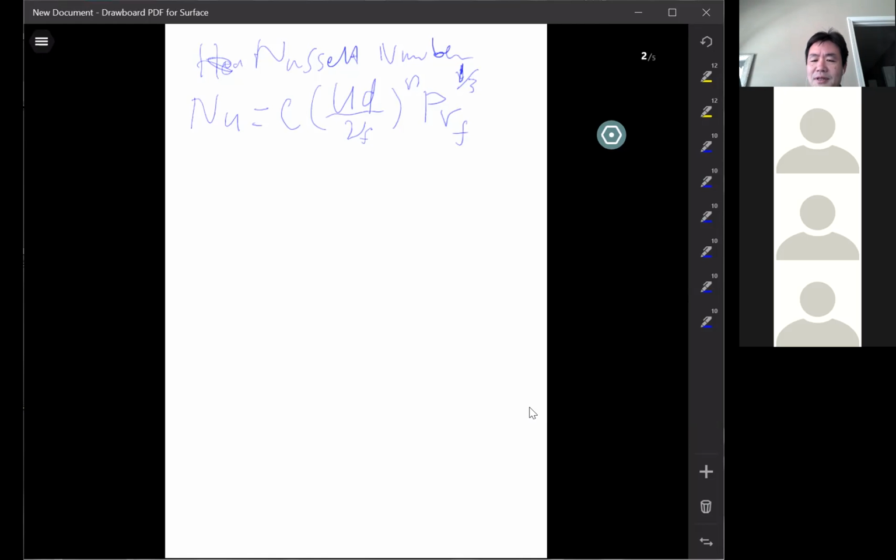Please follow me in my class. You see I give you a lot of quizzes like this. I just want to make sure everybody follows me, so you can save your time after school. I try to make sure you learn it during class time. The Reynolds number range for this equation is from 0.4 to 400,000, a very big range. With different Reynolds number ranges, you will have a C value and an N value. You need to calculate the Reynolds number anyway, to find the appropriate C and N, using Equation 6.17.